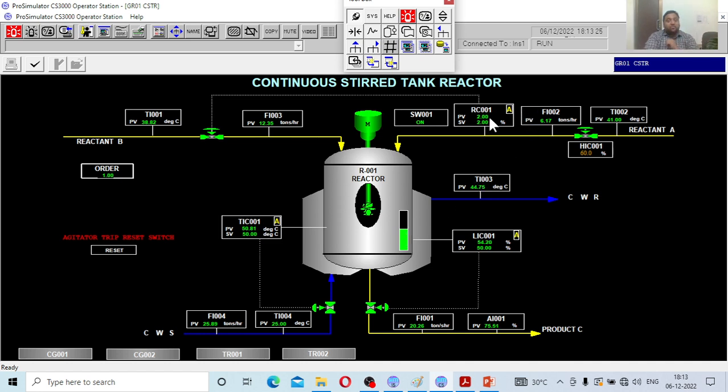What you have increased is the flow rate into the reactor. Of course, the conversion is going to get down if you increase the flow rate into the system, because the space time has been reduced. If the space time has been reduced, automatically the conversion is going to get reduced. That is the job. See, now the dynamics: initially it was rising, now it is dropping. So these are the dynamics you all have to understand, because even though you play with this particular system, what is going to be affected in the ultimate.